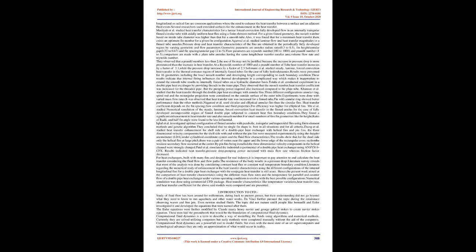The overall heat transfer coefficient is the overall transfer rate of a series or parallel combination of convective and conductive walls. The overall heat transfer coefficient is expressed in terms of thermal resistances of each fluid stream. The summation of individual resistance is the total thermal resistance, and its inverse is the overall heat transfer coefficient U.